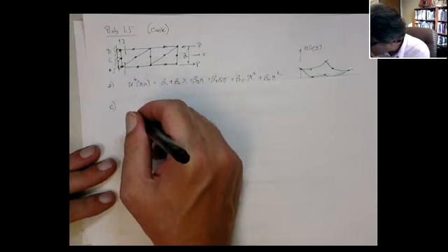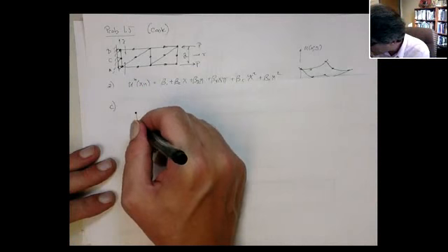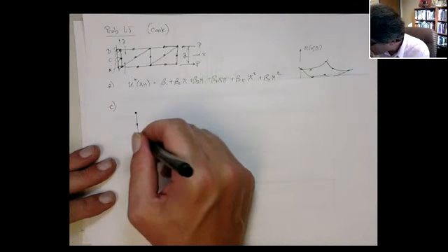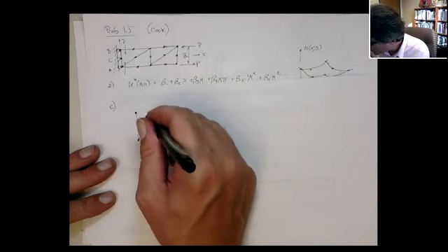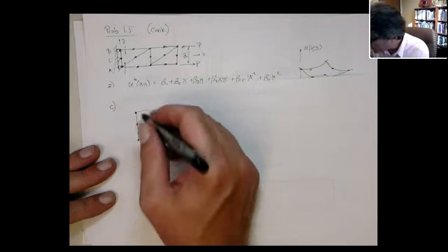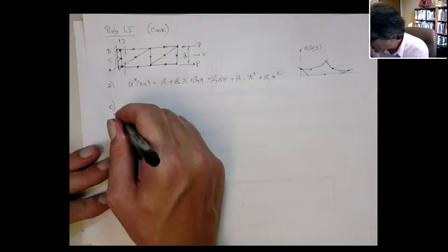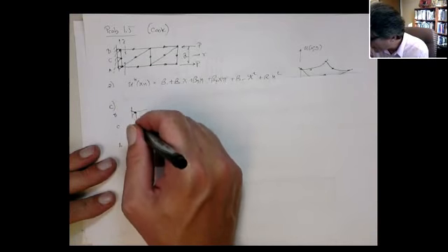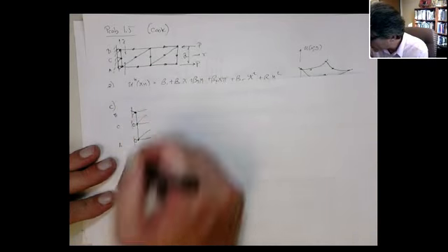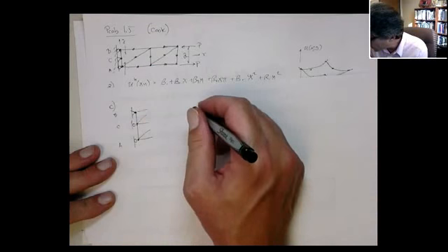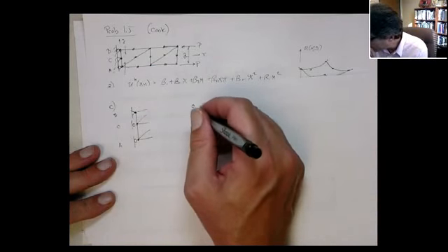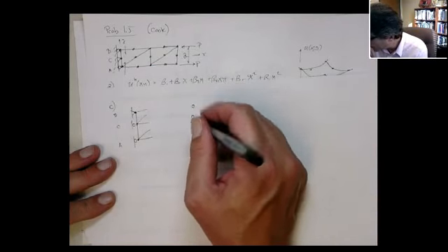So you could actually, on this edge, if these are the points A, C, and B, you could pin the top and put the bottom ones on rollers. That would work. You could also put the top two on rollers and pin the bottom.